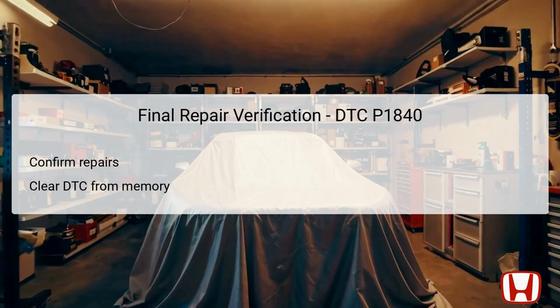Clearing this code resets the vehicle's diagnostic system, allowing for the collection of new error data. After clearing, it is advisable to conduct a test drive under various conditions to monitor vehicle behavior. This ensures that no further issues arise and confirms the successful resolution of the initial problem. The final repair verification is an essential step in maintaining vehicle integrity and providing the driver